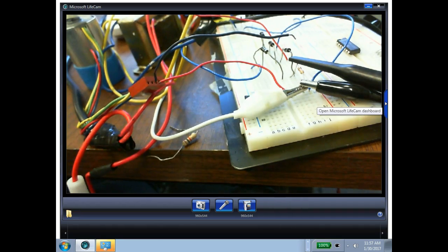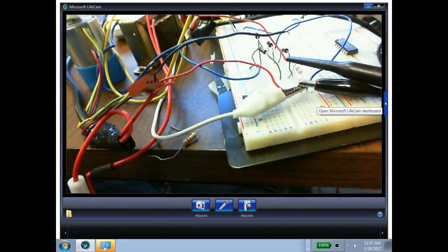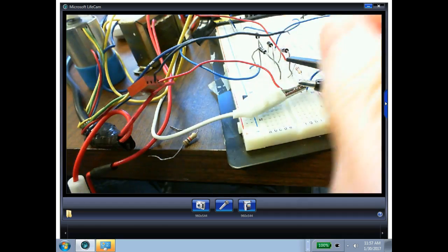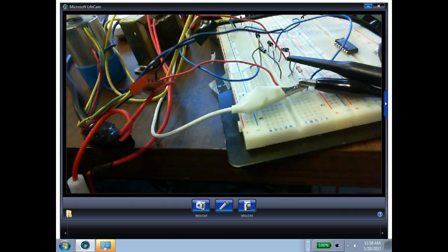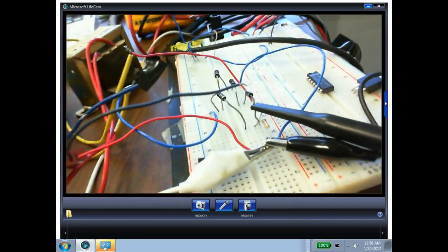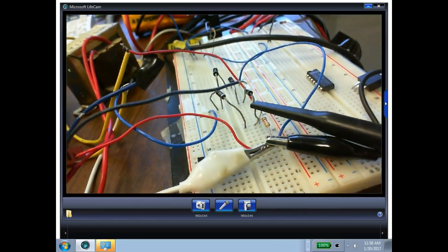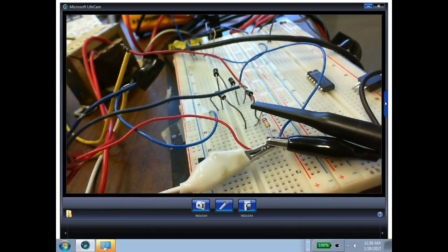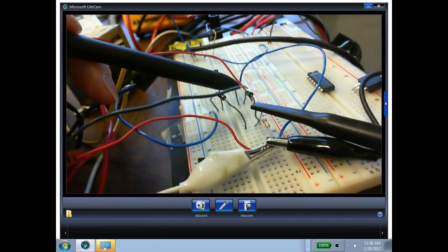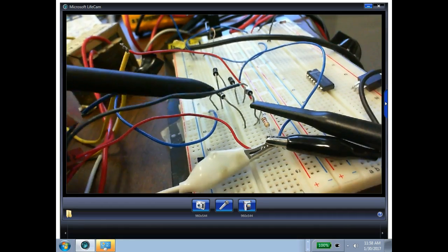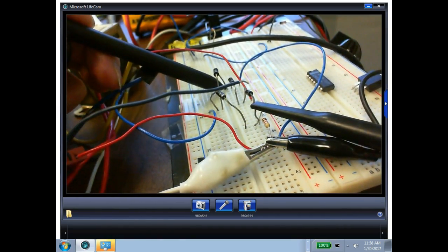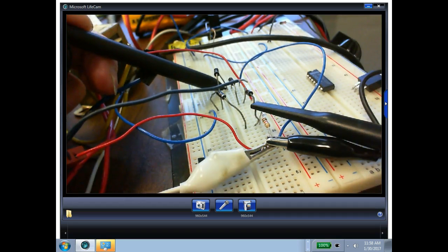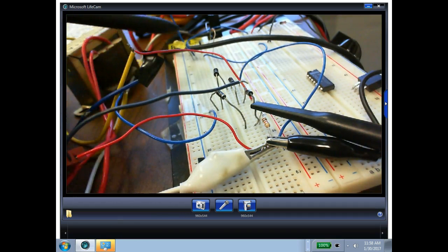So we got it up here. Here's my power supply. So here's my 4 diodes. I've got the anode cathode connected right here. These are connected together. And I went across the gap to make it easier. So here's an anode cathode connected together. I have the cathodes connected together up here and the anodes connected together right here. Okay. So there's my bridge.